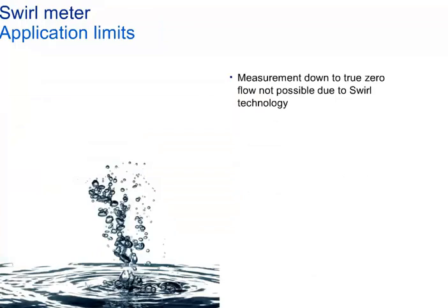As you have now learned how this measuring principle works, you can understand why flow meters of this type cannot start working from zero, contrary to electromagnetic or Coriolis mass flow meters, for example. A specific flow velocity is required to build up the internal flow system and be able to reach the linear range. As a result, a low flow cutoff must always be taken into account.